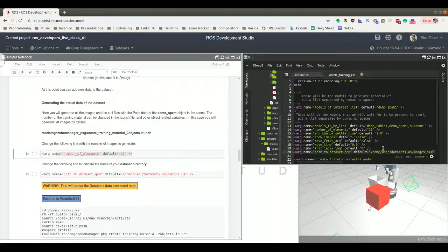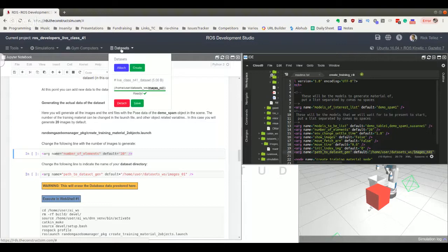If you have also provided a different name, then you have to put it here, the name of the data set. This one also corresponds to the one that, if I open here the data set, has to be the same one that is included here. You see this one there. Okay, so very simple. Once you have modified that value, you can press Control S to save, or go to File and Save.